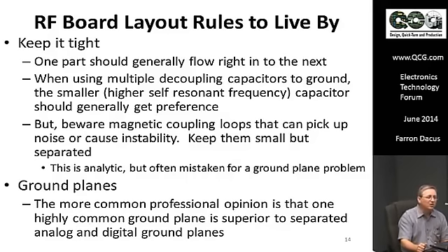You look at the spec on the linear regulator and it says you've got 55 dB of suppression at the switching frequency, so you're thinking, okay, I'm going to be 110 dB down on the switching noise on that supply to a sensitive point. Then you look at it and whoa, it's 40 dB down and not 110, and that is usually because of this magnetic coupling loop that's not in your simulation. You've done a good SPICE simulation in every regard except that magnetic coupling loop.